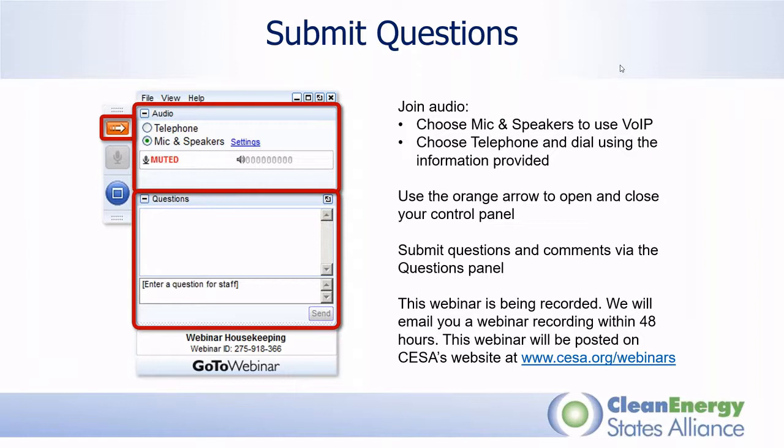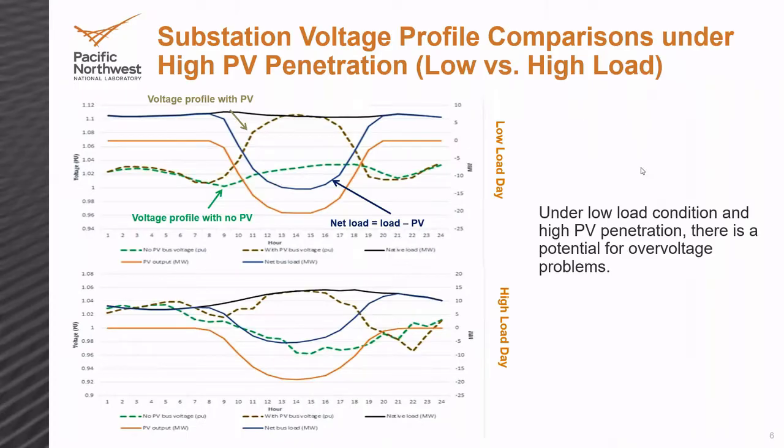Great, thanks. This next question relates back to slide 6 or 7, so I don't know if we can scroll back to those slides. But the question is, even with no PV, the graph still shows voltage violations. This snapshot shows the PV making this problem only slightly worse. What is the worst added overvoltage caused by PV that you've seen? That is, the biggest gap between the blue and the green lines.